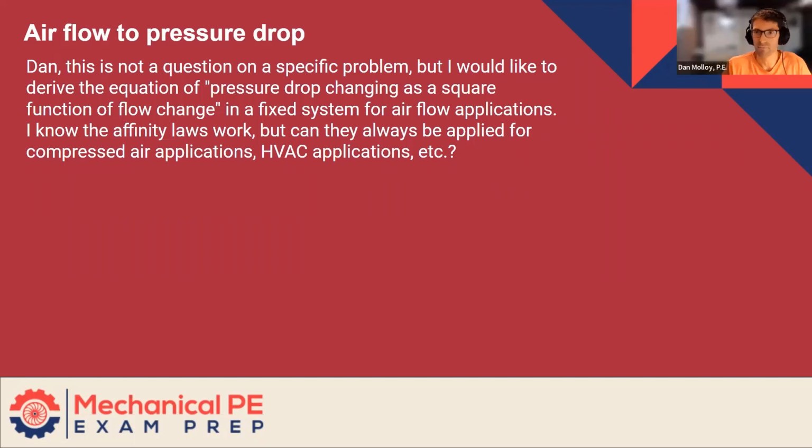Yeah, now that you've asked, it's making me wish I had a deeper, more fundamental explanation for why that is. I've sort of just taken it as a given too. That the speed and the volume flow rate are linear. The pressure goes with the square of either of those, and then the power goes with the cube. Good enough for me.